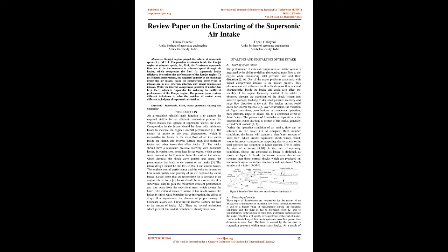Like external losses of intake, it has inside losses like losses in shock wave boundary layer interaction, the effect of drags, flow separations, the absence of proper mixing of boundary layers, etc. These are the internal factors that lead to the unstart of intake. There are several techniques which prevent this unstart, which have already been done.